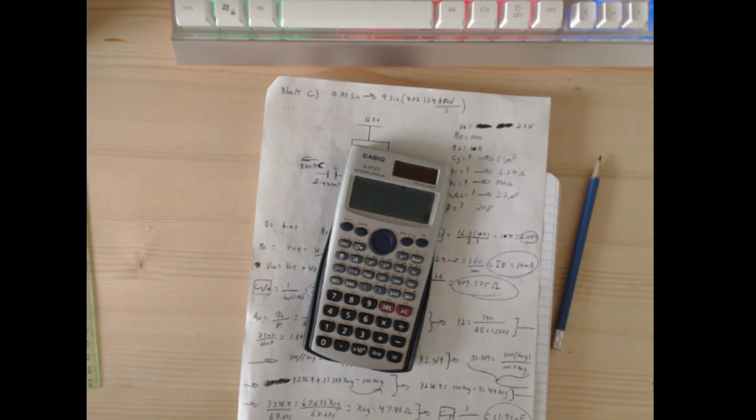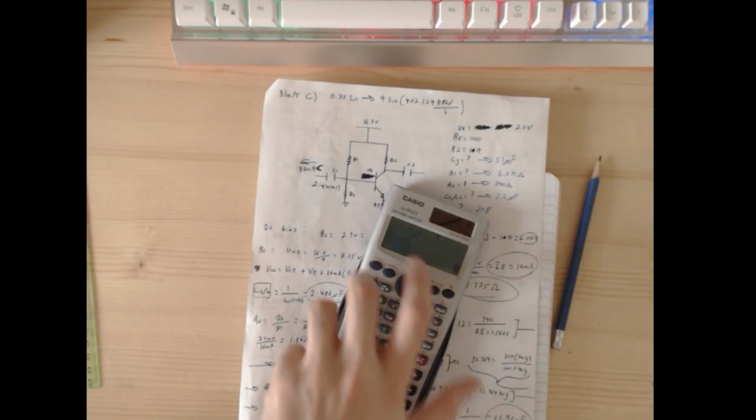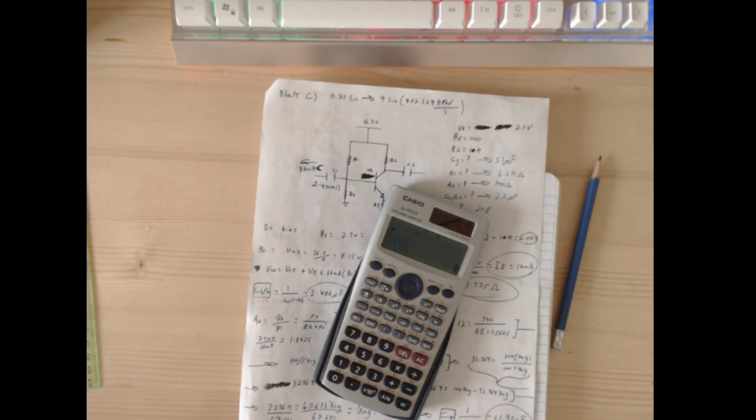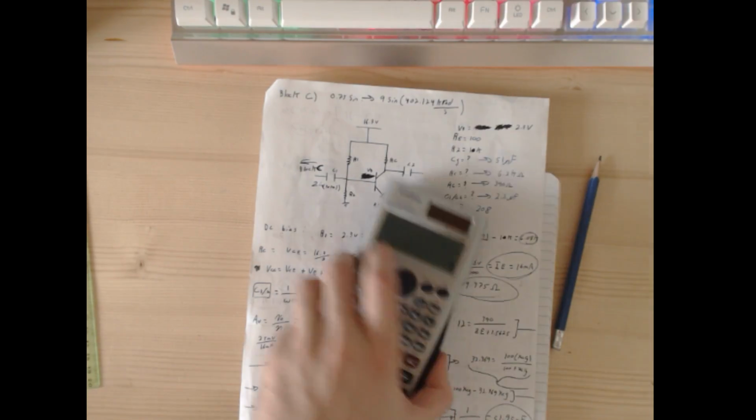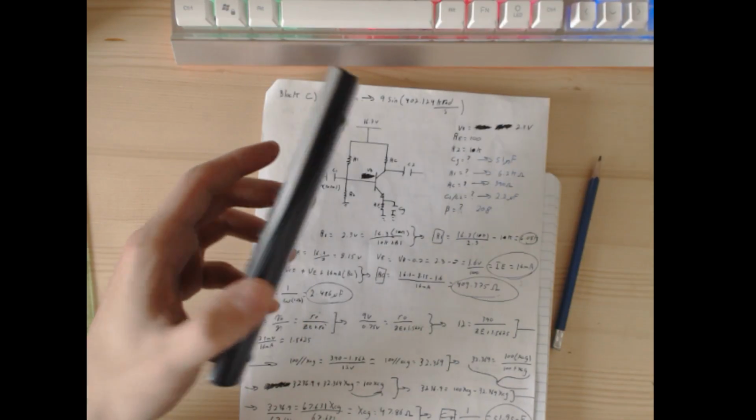Where R2 is a voltage divider resistor from base to ground. If this requirement gets ignored, the amplifier might not work due to loading effects. So 10 R2 has to be less than the Z in base. So I need my R1 to be very low.